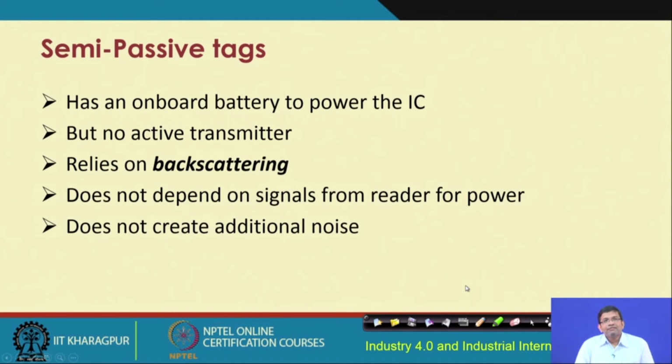There are semi-passive tags as well, which have an onboard battery to power the IC that is embedded inside these tags, and there is no active transmitter, but this mechanism also relies on the backscattering concept that I discussed previously for the passive RFID tags.